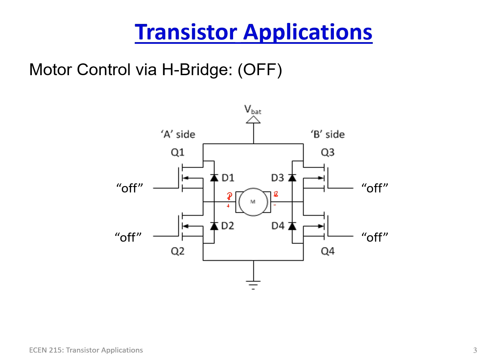So if I turn off this transistor, and in this case, everything is off. If all these transistors are off, the motor is not connected to anything. Remember we learned about MOSFETs the other day in the previous topic: if they are off, then there is no current flow. All of these RDSs are infinity ohms, so it's basically as if the motor is not connected to anything. The wires are just hanging in space.